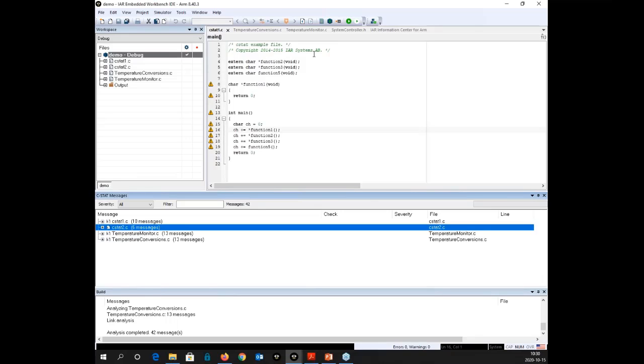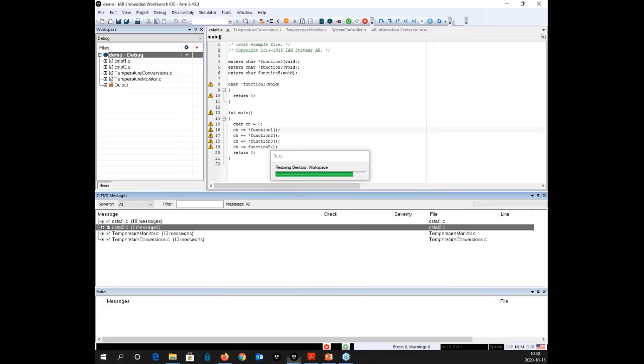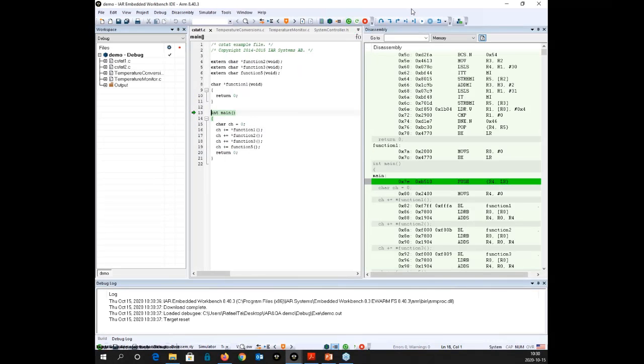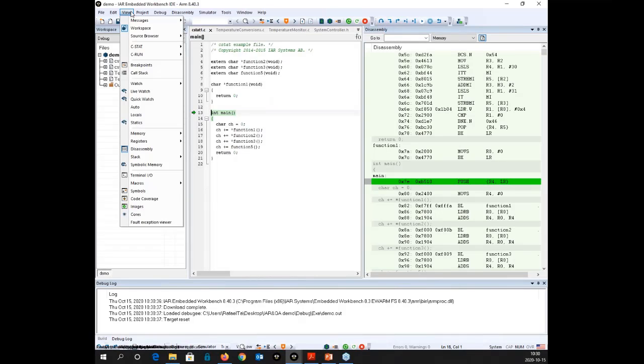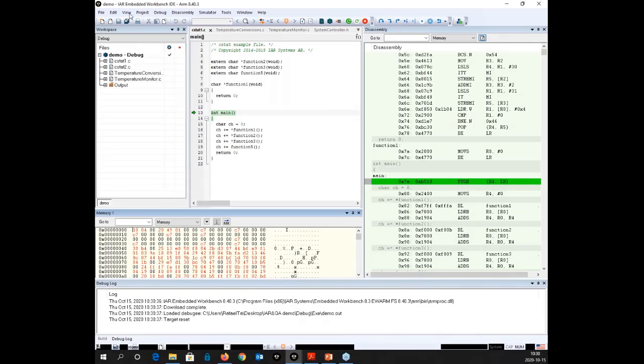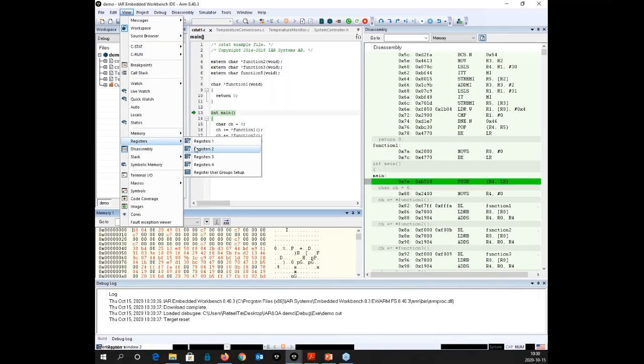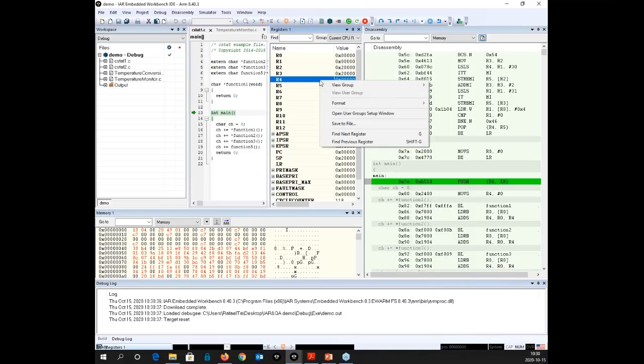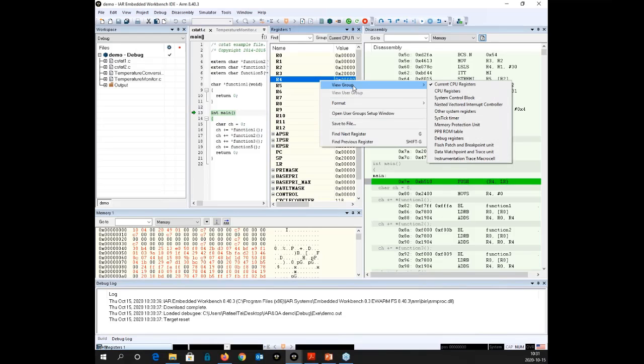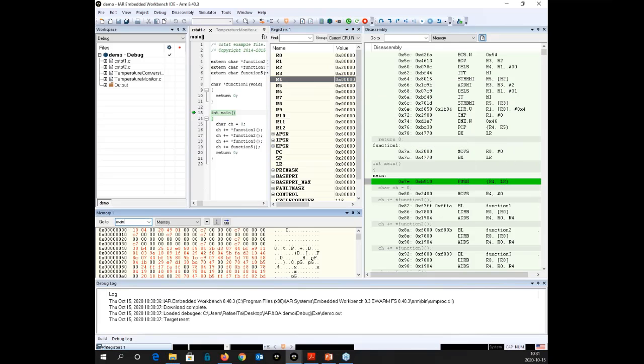And as I said, once you have the device, it will know exactly what's on the other side. And mainly what you can do, as I said, is connect here to the debug session. And then, of course, everything that is available will appear first here under the view option to watch into memory, registers, for example. You can navigate very straightforwardly here. If you look at specific registers, we could check here all peripherals or what we want to investigate here on the memory. If you just type some symbol, it will take you to that address.